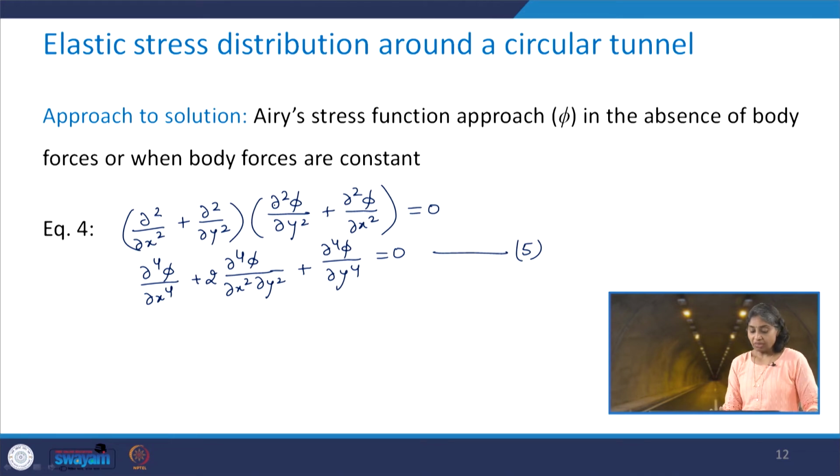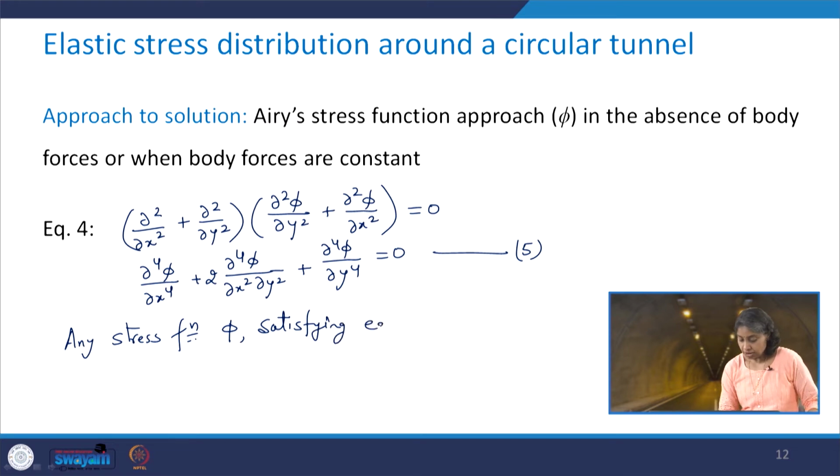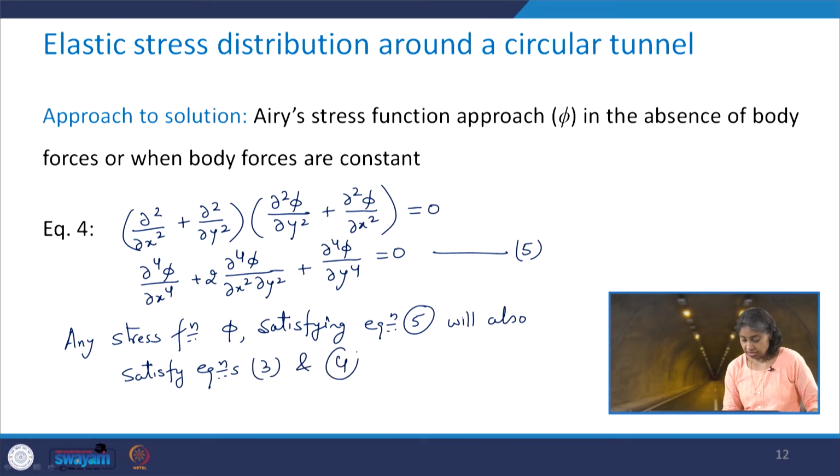So, any stress function phi, if it is satisfying the equilibrium condition, has to satisfy equations 3 and 4 as well. So, the situation here is that any stress function phi satisfying equation number 5 will also satisfy equations 3 and 4.